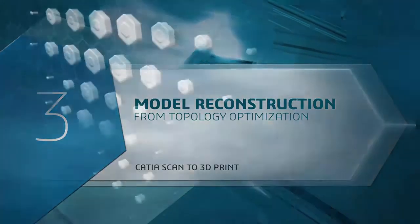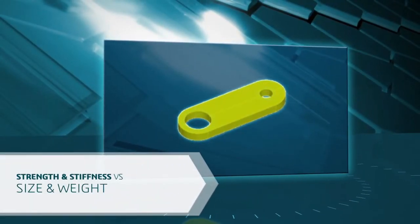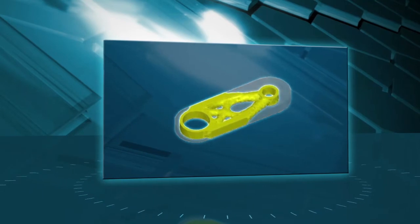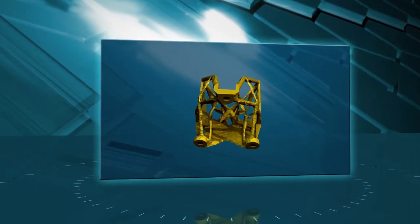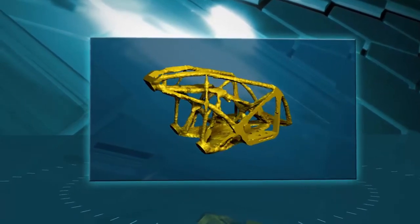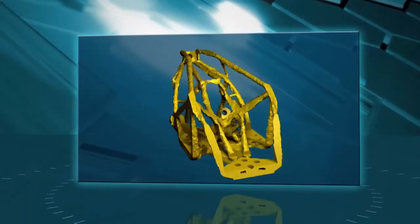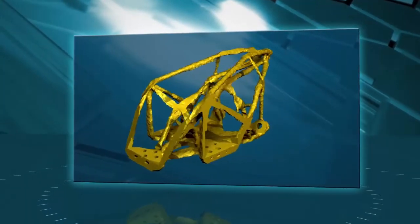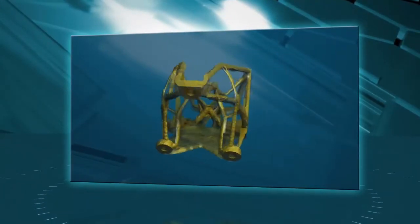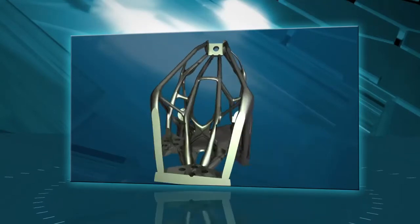When designing a product, there's always a trade-off between performance requirements for strength and stiffness versus size and weight. Recently, tools have become available to help in optimizing a part's topology, like Simulia Tosca, for example. The result is a very organic shape, which can be produced using 3D printing. There would be no chance with conventional manufacturing methods. But today it can take a minimum of a few days to several weeks to reconstruct the CAD model from the result of topology optimization.